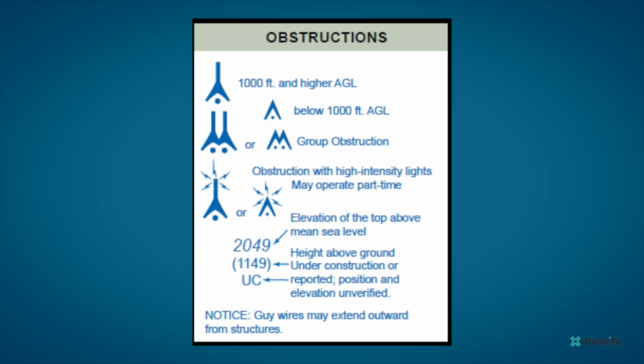For example, a drone pilot might need to maintain a minimum altitude above the ground in order to avoid obstacles such as trees, buildings, or power lines. This altitude would be measured in AGL. However, the FAA also sets altitude restrictions based on MSL in certain types of airspace, such as Class B, C, and D airspace, which are designated around airports and other high-traffic areas. Drone pilots operating in these areas must comply with the altitude restrictions set for that airspace, which are measured in MSL.